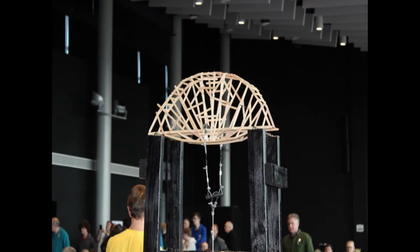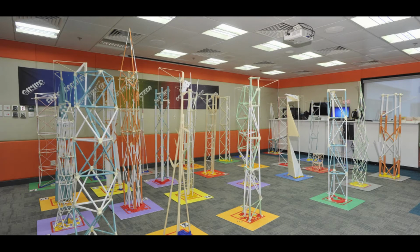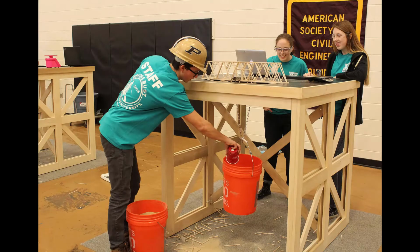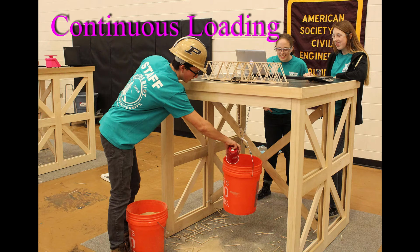So in the engineering world, there are plenty of competitions that involve building the best bridge, building the best tower, and then breaking those things. So once you've been around that for a while, you understand that there are a couple different ways to load model bridges. One of them is called continuous loading. This is where you suspend a bucket of sand and then you continuously pour the sand into the bucket, and you measure very precisely how much sand is there, and then at the end of it you get a really precise measurement as to how much weight your bridge could take before it failed. So that would be an ideal situation that we would do at the riverfront if we were able to put on a regular Engineers Week for you guys.